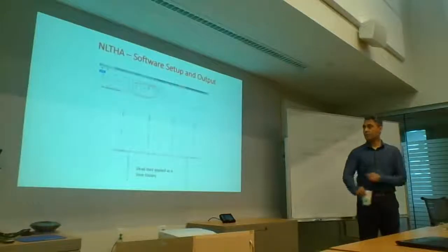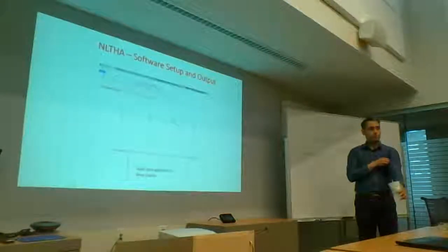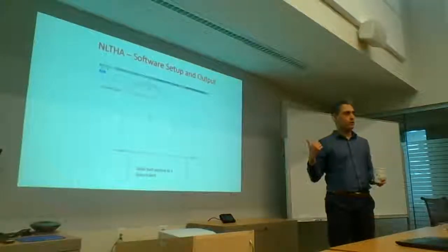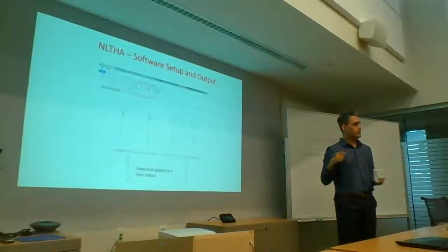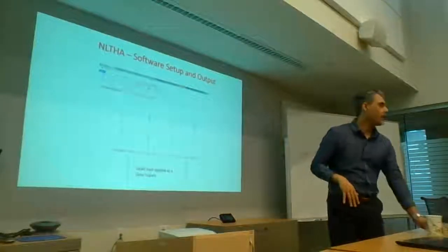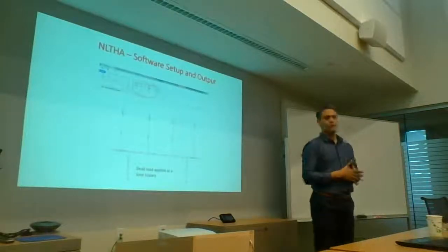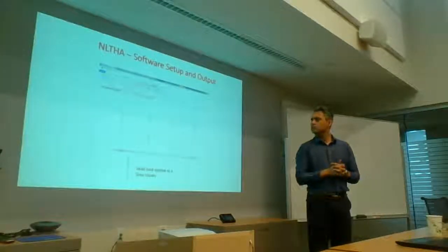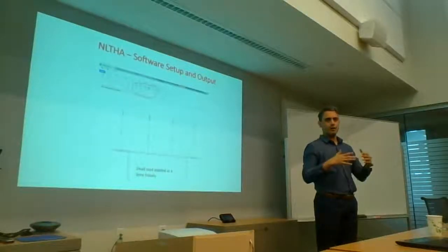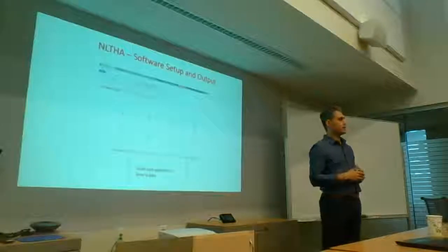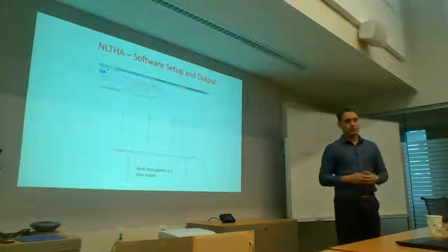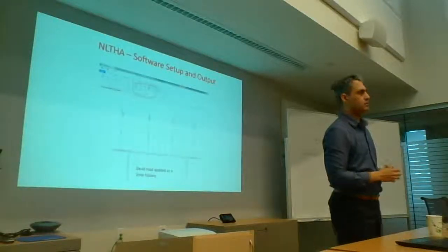So when we're doing a time history analysis, I'm not sure about other software, but you apply the dead load as a time history as well. That's just how this particular software works. It doesn't let you apply it as a static load. So how would you apply the dead load as a dynamic load and not get a lot of vibration and just spurious effects out of it? Because it's a very slow application. But we're going to apply it in a dynamic fashion.